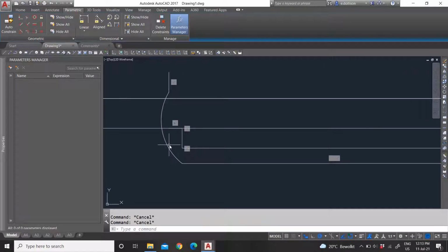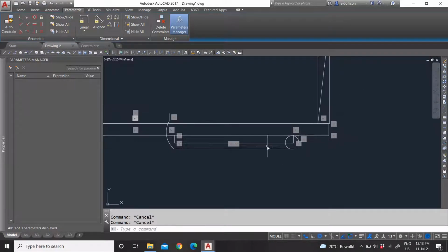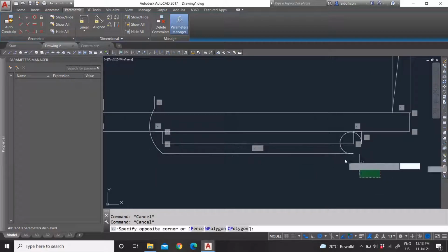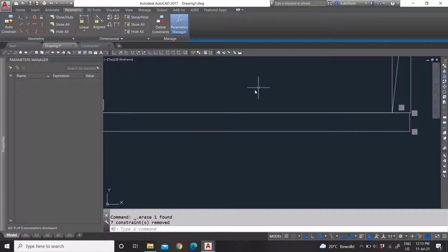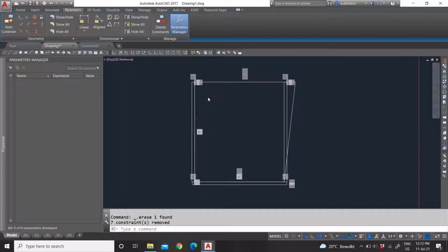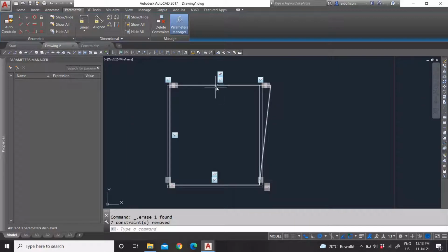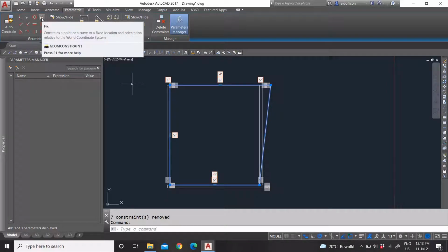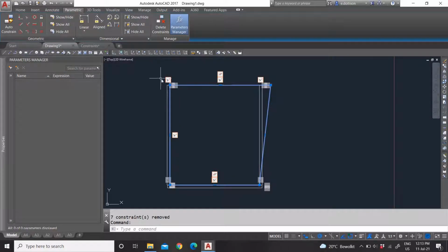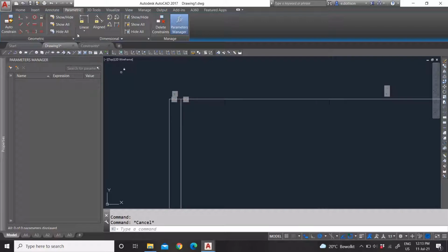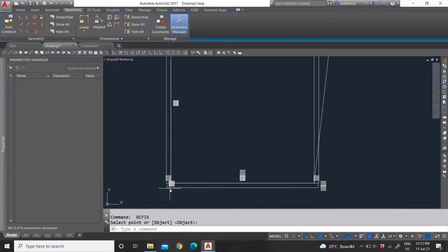Yeah, guys, sorry, you have to play with it a little because we haven't constrained, we haven't done anything about this right here, so it's kind of loose. So sometimes it's better just to delete it. Now, to avoid the line from going the other direction, what we can use is this lock right here. What this lock does is just fix a line or a point to make sure it does not move. So now I want to lock this point right here.